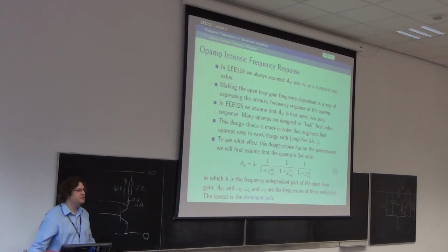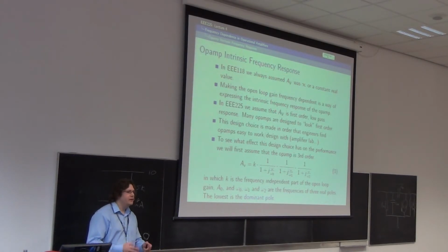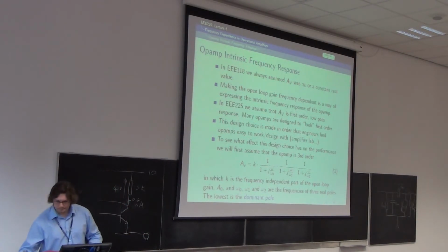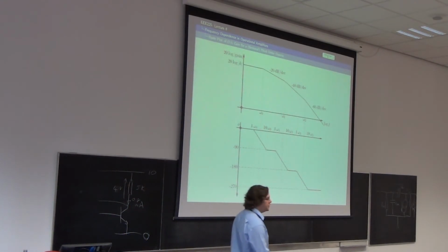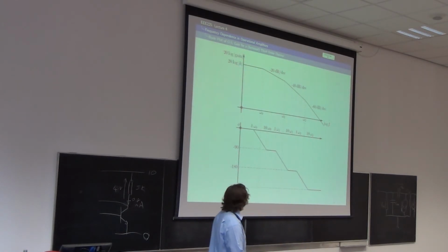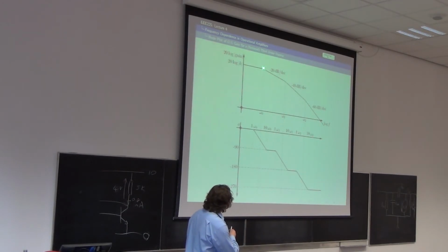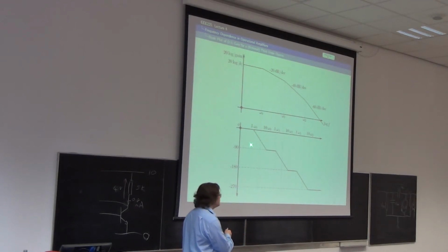It's really, really important in circuit design to be very flexible between the time and frequency domains, and when you're in the frequency domain, to have a good feel for what's causing the poles and zeros. So this is a Bode plot of the third order system, and it just so happens that I'm going to call it an op-amp. Actually, it could be any third order system that has 3 real poles. I have a pole here, and I'm saying that's 3 dB below that point. The fact that the line is very nearly straight is neither here nor there. And at this 3 dB point, I ought to have minus 45 degrees of phase shift.